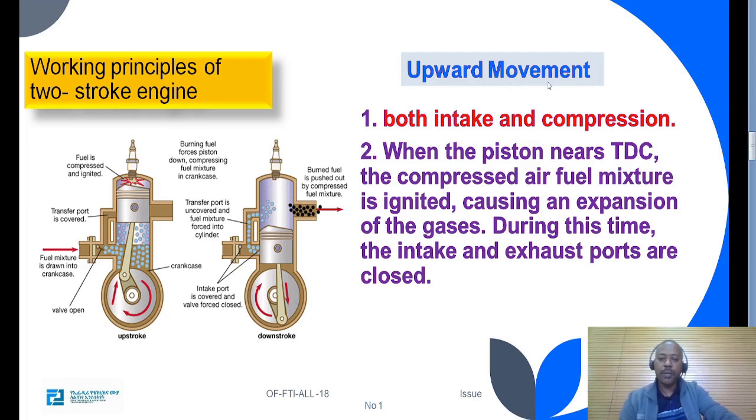Let's discuss the working principle in the upward movement. In the upward movement of the piston, both intake and compression processes take place. When the piston nears TDC, the compressed air-fuel mixture is ignited, causing an expansion of gas. During this time, the intake and exhaust ports are closed.